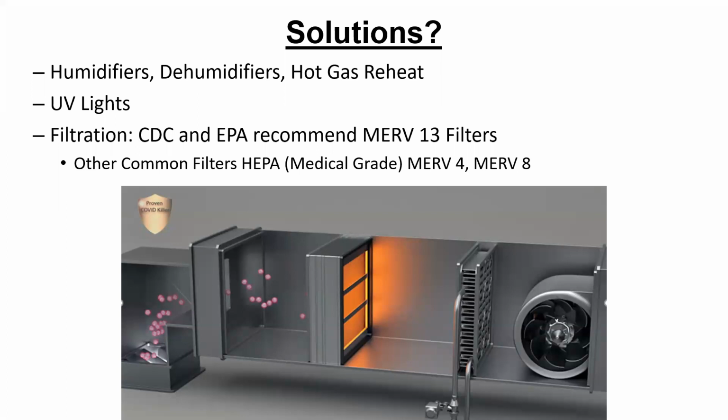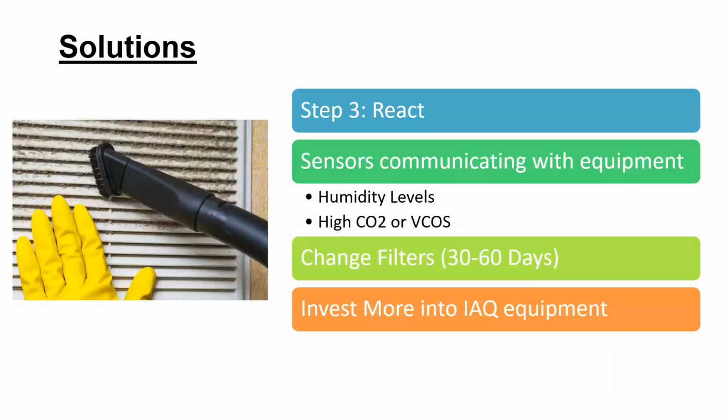Filtration is another important thing. You want to make sure your filters are regularly changed. The MERV number, MERV stands for Minimum Efficiency Reporting Value. 13 is used for hospitals, so medical grade. It probably cannot be found in stores for building or residential use, but MERV of 4, 6, 8 are totally fine as long as we change them regularly. Every 3 months would be an idea.